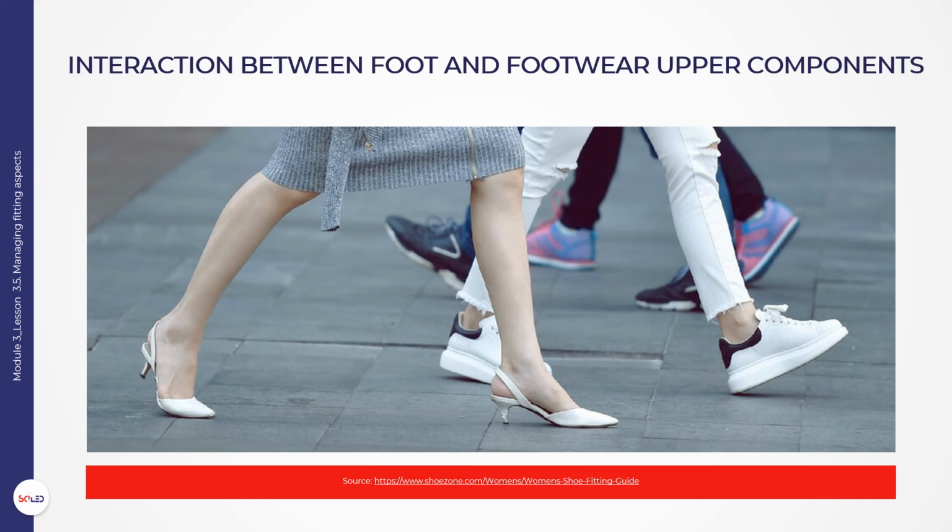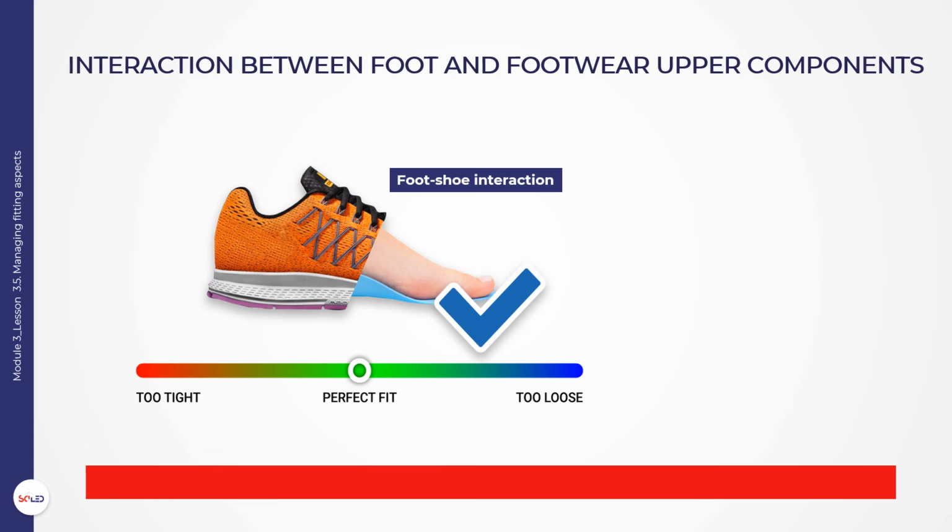Tight tolerances practically do not exceed 2 mm. Beyond that value, the user experiences compression of the tissues and discomfort since blood circulation is disrupted. There is a wide pool of lasts covering most applications and sizing systems around the world. In practice, most industries resort to last modifications and trial and error fitting trials until they achieve the desired results.